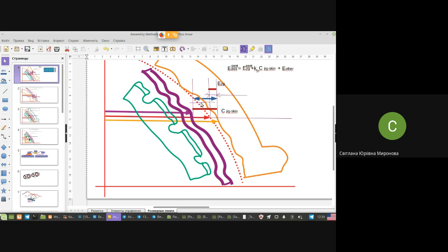Yeah? It's produced once and more accurately than some hundred of skins. Moreover, when we are trying to repeat the surface of the locator, we increase interchangeability of these panels of the skins, because they are not so different any longer. They are more similar, not even to the theoretical outline. Yes, maybe this locator is not ideal. It does not ideally repeat the theoretical outline, but at least all the skins will be more similar to each other, more interchangeable. And in terms of coordination, it would be better.